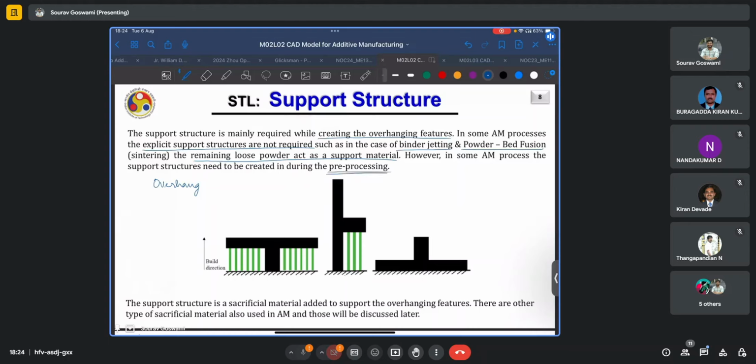So while we are still on our computers, working through the design and generating the final G-code file which will be printed, the support structure, as we know, is a sacrificial material. Such a sacrificial material can be made of a different material, typically weaker, or it can have a lower density, or it can have some other properties.